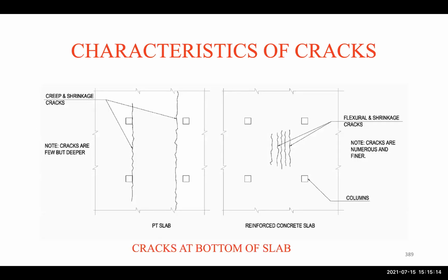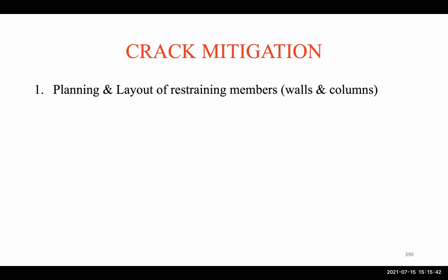Everything is summarized in this figure. On the left hand side, we have the PT floor, so you can see how the cracks are developed here. They are wider, longer, and deeper. On the right hand side, in the typical reinforced concrete floors, cracks are typically shorter, shallower, and closely spaced. So that's the nature of the cracks.